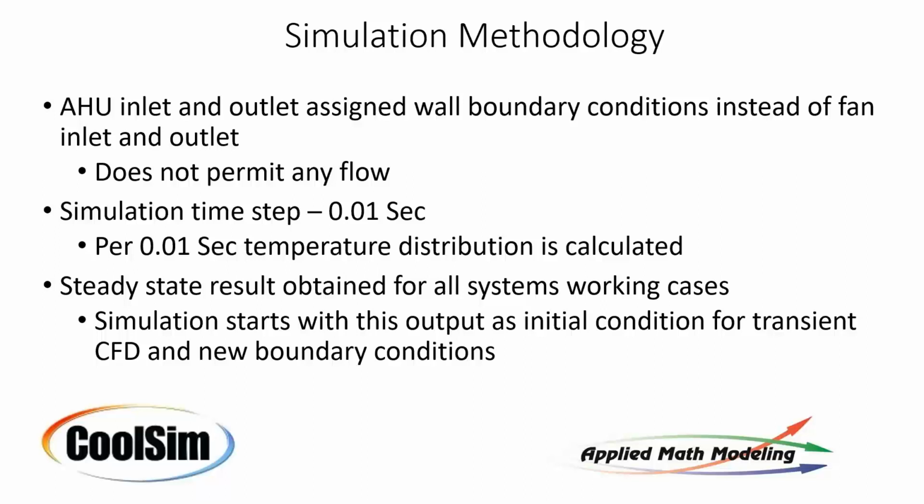We have a simulation time step of 0.01 seconds, which means we need 100 of these to give us 1 second. Another thing about transient is, from a CFD point of view, it's computationally intensive. You have to do a full steady state solve at each time step. So for 1 second, I have to do 100 solves, and each solve can take a couple of hours. So the amount of time required to do these analyses is long and computationally intensive. But it can be done, and the results are fairly representative of real-world situations.